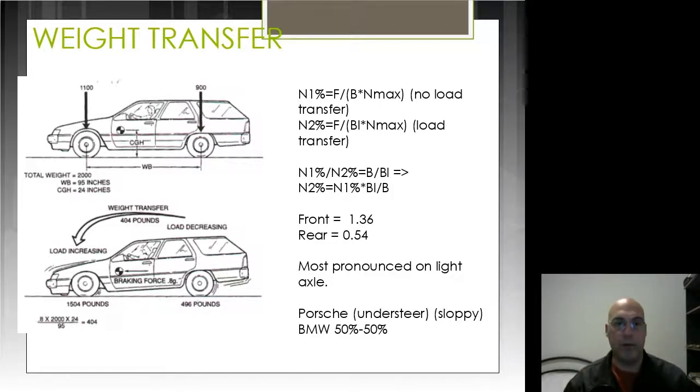So in this picture here, where the center of mass is towards the front, you have a bigger problem with weight transfer when braking. So front-wheel drive cars, braking into corners, you will feel they are a bit unstable. Porsches, for example, would be great braking into corners because the weight is on the rear. You won't have that problem with the weight transfer to the front. You'll have the weight transfer to the front and it will make the car very stable.